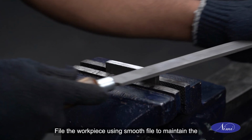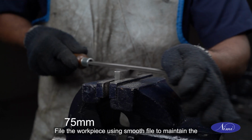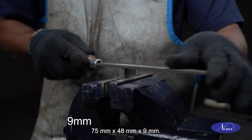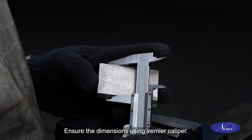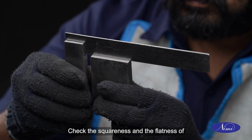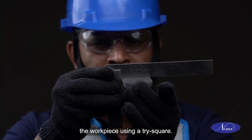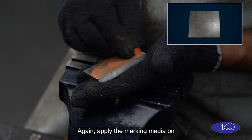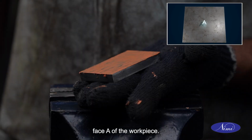File the workpiece using smooth file to maintain the 75 mm into 48 mm into 9 mm. Ensure the dimensions using vernier caliper. Check the squareness and the flatness of the workpiece using a tri-square. Again, apply the marking media on face A of the workpiece.